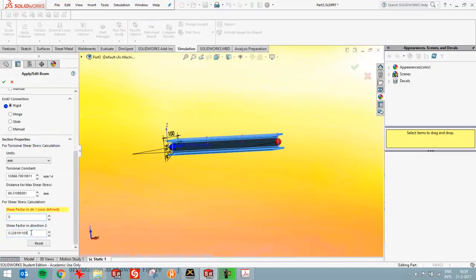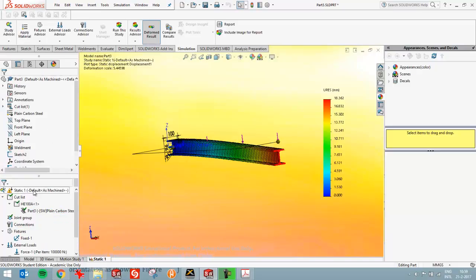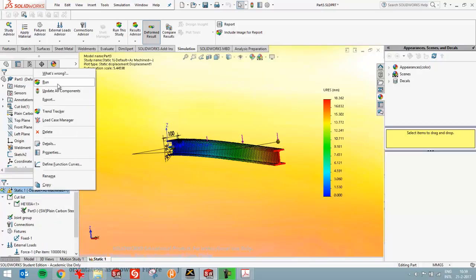Actually, you shouldn't do that. Actually, your FEM analysis is more accurate than your hand analysis, because your hand analysis doesn't take the shear effect into account. And with short beams like this one of just 1 meter, that makes a considerable amount of difference.